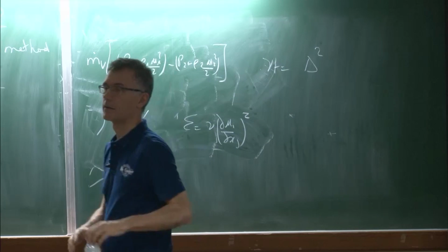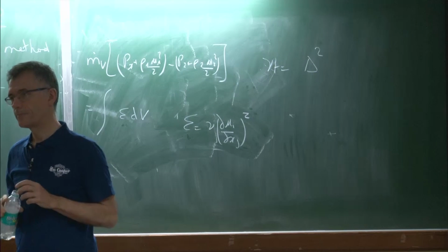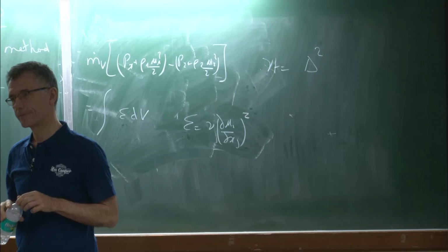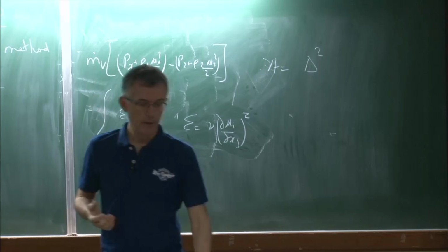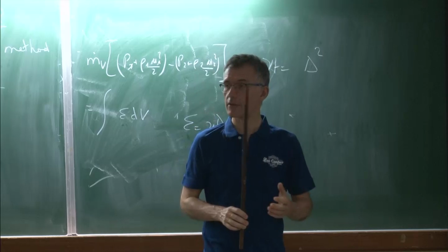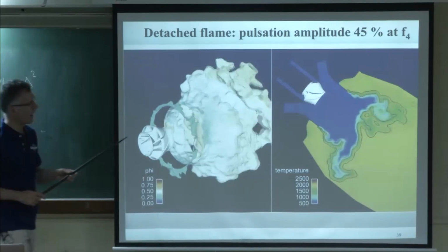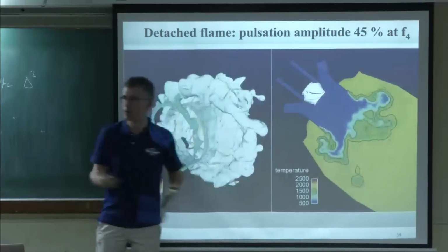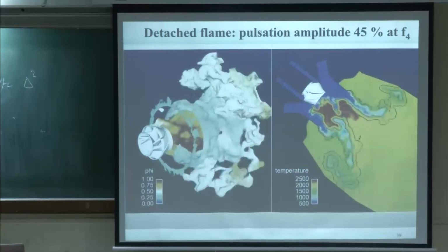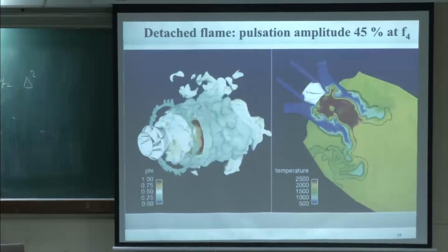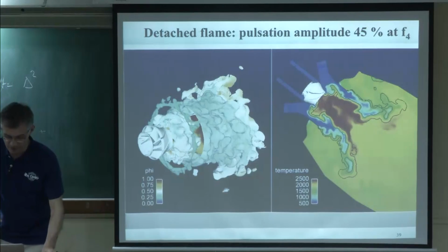Where there is not just acoustics and flame interaction, there is hydrodynamic instability as well because of the pilot flame. So is that the case where you're showing the hydrodynamic instability is also because of the gas turbine? Well, this flow is full of hydrodynamic instability, okay? You have vortices everywhere. So yes, here you have thermoacoustics and vortices. You can see vortices everywhere. So it's a clear case where hydrodynamics interact with thermoacoustics. Actually, the largest animal there in terms of hydrodynamics is the PVC. The PVC is really playing a big role in this business.